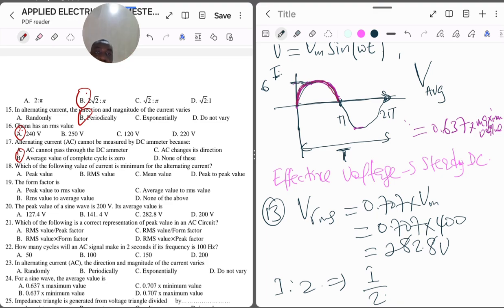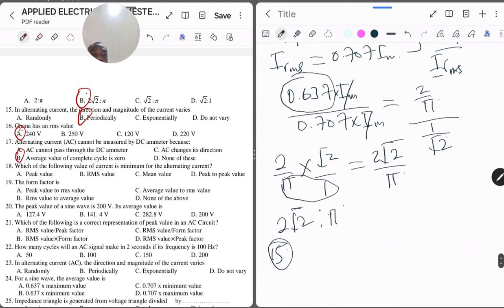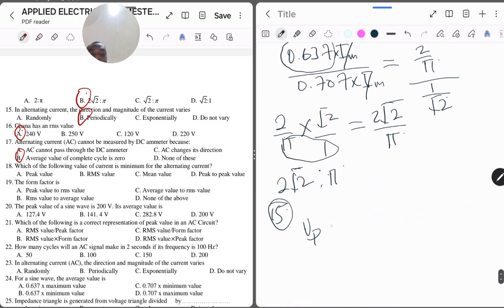So if I am given peak value, we know peak value is the same as what? The maximum value, meaning Vm. So we can say that Vp is equal to Vm, right? Now B, which is root mean square value, we also know in terms of the maximum value. So let's say in terms of voltage, the root mean square voltage is what? 0.707 times the maximum voltage.